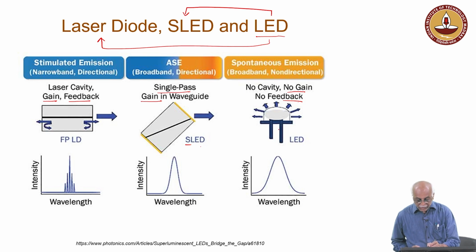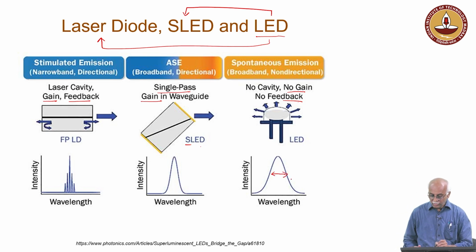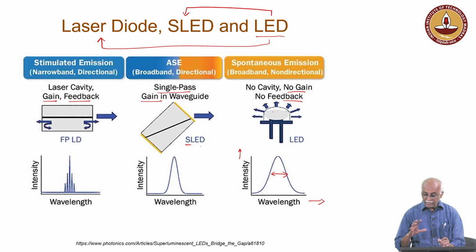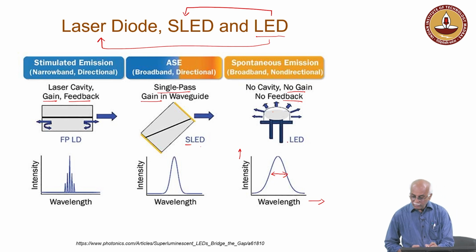Secondly, if we see the LED or SLED, it has a spectral bandwidth. Okay. So, x axis is wavelength, y axis is the emission intensity, and it has a bandwidth. This bandwidth is decided based on the band gap configuration. And we will try to estimate the approximate bandwidth, which, depending upon wavelength, will again vary, is around a few tens of nanometers. Okay, bandwidth will be available.